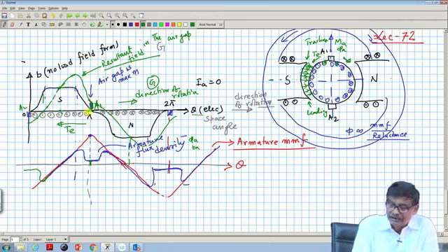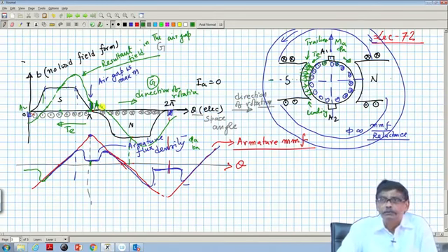That legacy of this dot current in a scenario when armature carries current still continues when the conductor reaches here, because it is still south pole. The polarity of the induced voltage, hence currents will be this dot, but the moment it crosses, it has to carry cross current, that is the destiny for these conductors, the way the windings are done. Therefore, the commutation will be delayed.